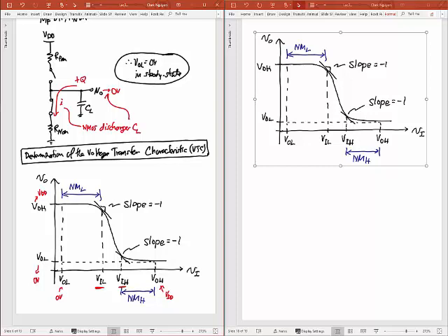And so the reason why I care about that noise margin is because, say my voltage was at 0 volts, but say some switching event happened nearby, I can get a spike of voltage here that, if large enough, can actually switch this thing to the other side. And if this were feeding a flip-flop, that flip-flop would be permanently switched to the wrong bit. Okay? And so this is what we're going to do next time, but we're out of time right now, so I'll see you on Wednesday.